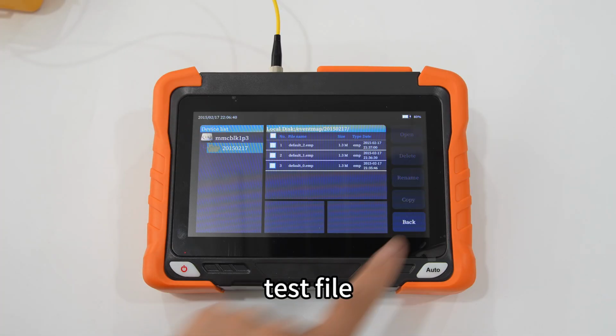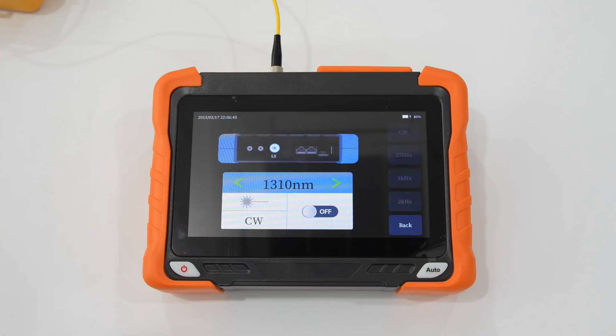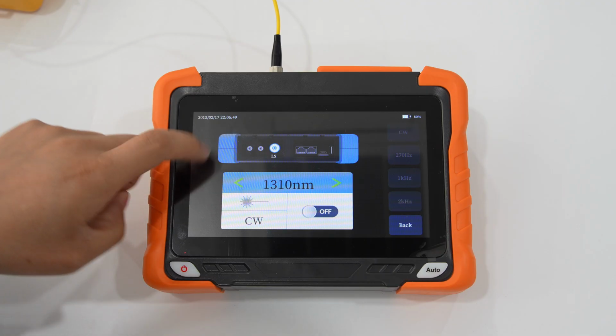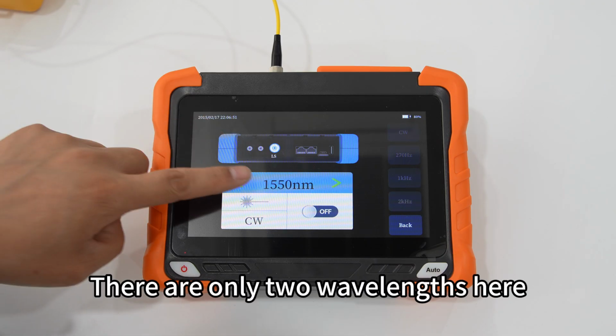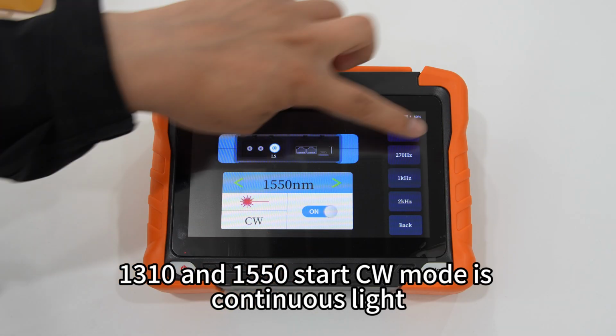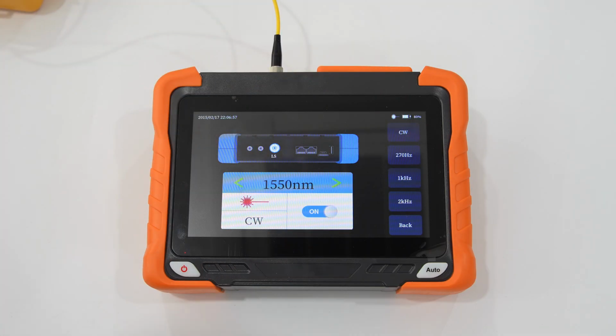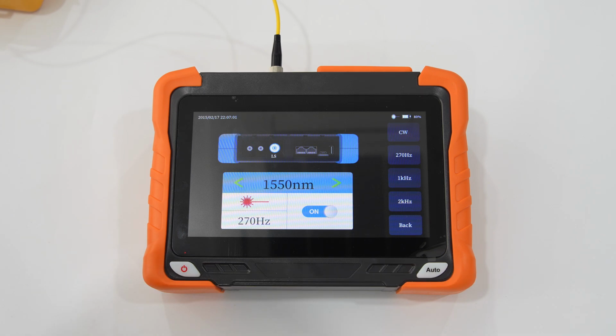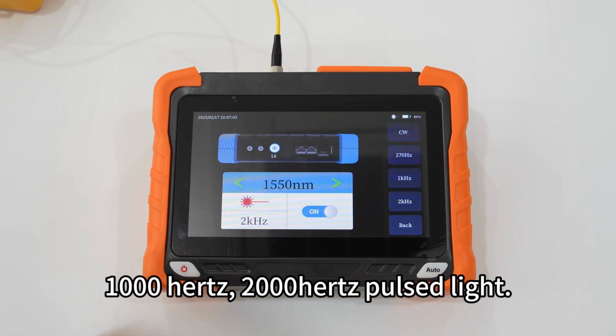Test File. Light Source. Different lasers support different wavelengths. There are only two wavelengths here. 1310 and 1550. Start. CW mode is continuous light. 270 Hz is pulse light. 1000 Hz, 2000 Hz pulse light.